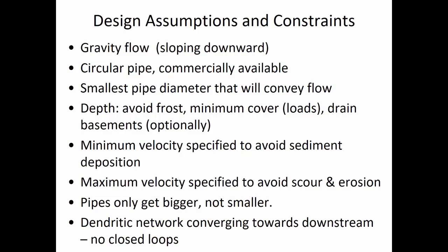And so what you wouldn't want is you wouldn't want a pipe that's, say, an 18-inch pipe to discharge into one that's 12-inch, because that means whatever debris is making its way through the 18-inch pipe has to encounter a bigger space, not a smaller space. Otherwise, there's a much higher risk of clogging. And so a little ball sometimes would be flowing through the 18-inch pipe, and it's got to get into a bigger pipe. So the pipe should only be getting larger.